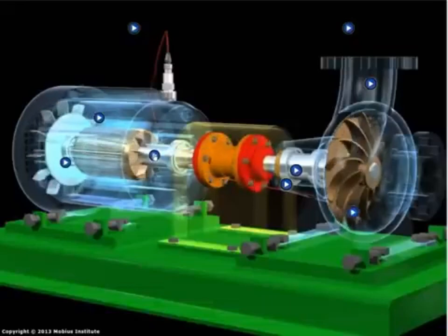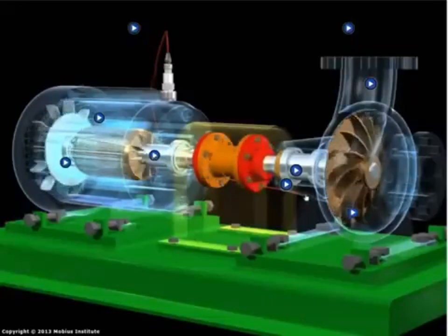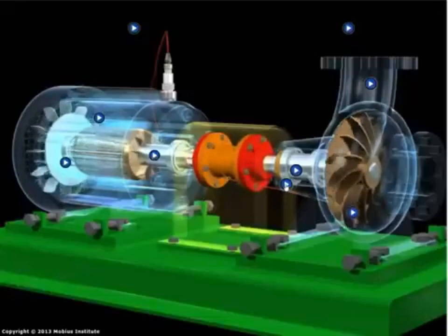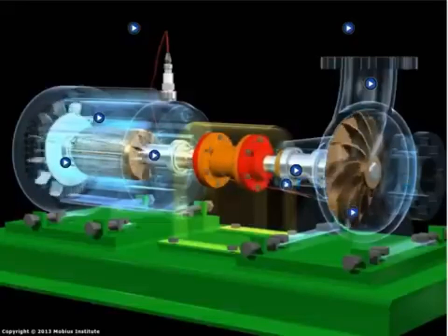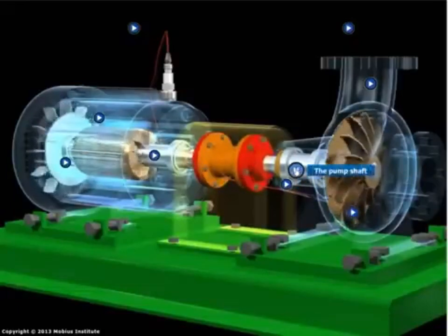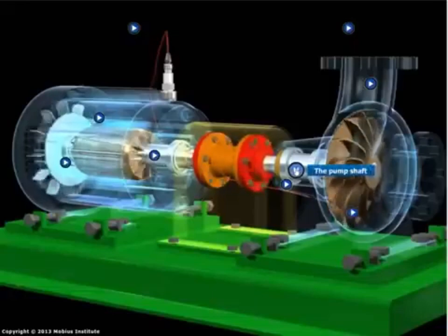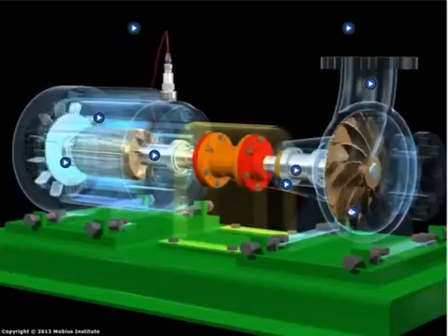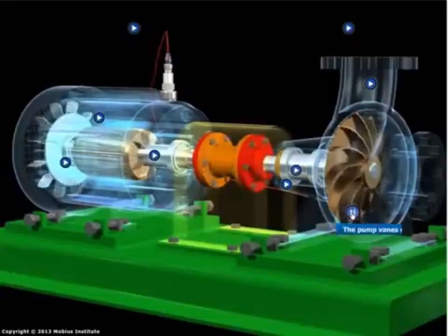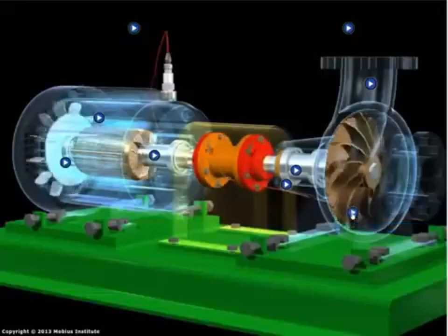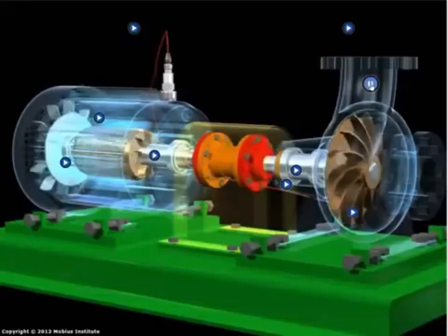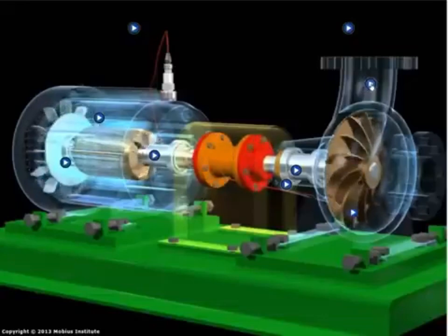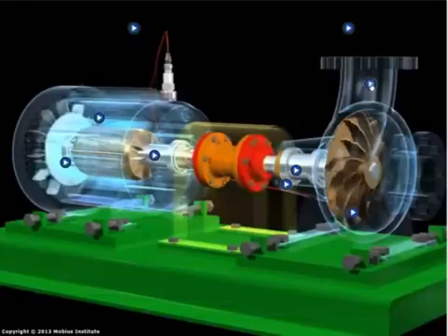Now, I'm just simulating the sounds. They'd actually be more pure than that in reality. But if there was a problem with the bearing, we're just listening to it, but the vibration pattern would change. If there was a problem with the alignment, balance, if the shaft was bent or something like that, we would see it. If there was a cavitation problem, well, we would be able to detect that through vibration analysis as well. And if there's a problem on the machine head, I wish all machines made that sound, but yes, we could detect that too.